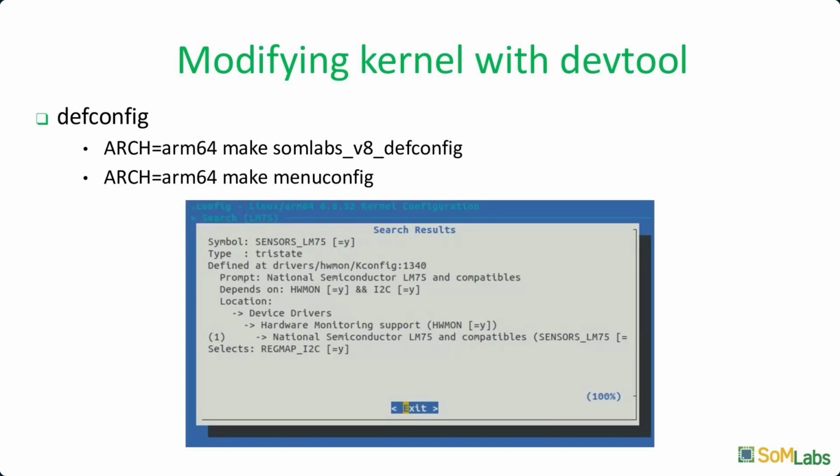Like here you can find, for example, SENSORS_LM75. This is the driver of the hardware monitor, the temperature monitor, that has a driver for the kernel, and this way you can select it to be built together with the kernel. So this mechanism is completely independent from Yocto.